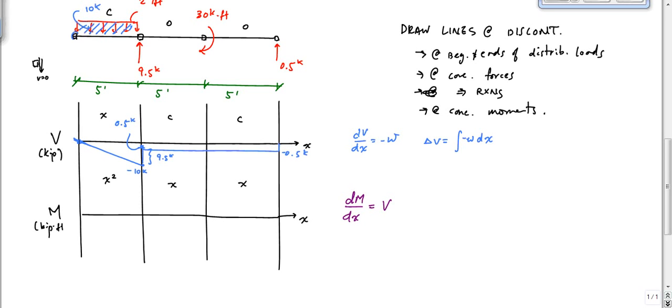All right, that's good. Okay, so now I also know that here, if I go back to this little joint right here, because I have no loading here on this joint, this moment is 0, so I know I start at 0 here. Okay, and in general, when you have a free end, you're always going to start at 0. This is a free end. So you start from 0 here.